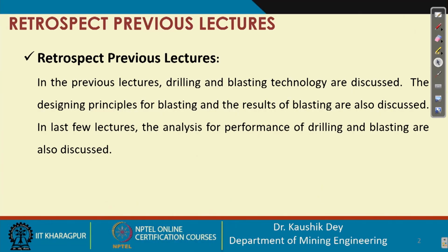So far we have covered more or less the theory part, which is drilling and blasting, the practice carried out in surface and underground mines. In surface, it is basically bench blasting. In underground mines, we have discussed the blasting carried out in the drives and drifts in the mine, and different drilling patterns and blasting patterns are also discussed.